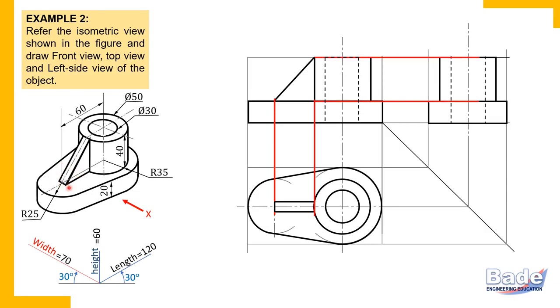And thickness is to be measured parallel to the width axis. Parallel to width. And in the top view, width is vertical. So measure a width of 10 millimeters. Watch here. So draw end projectors of the triangular plate, from the right end and left end of the triangular plate. And in between the projectors, you are going to draw the top view of the triangular plate. That is the rectangular strip.